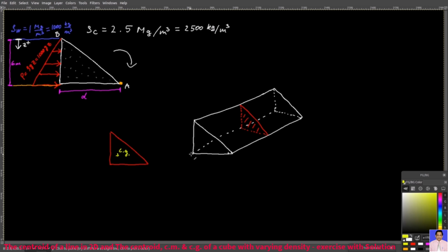So we are not concerned with finding the center of gravity along the width of the dam, but rather we are taking a cross section of that dam, which in our case is the same everywhere. We have the cross-sectional area of the dam and we try to locate the CG in that cross-sectional area.